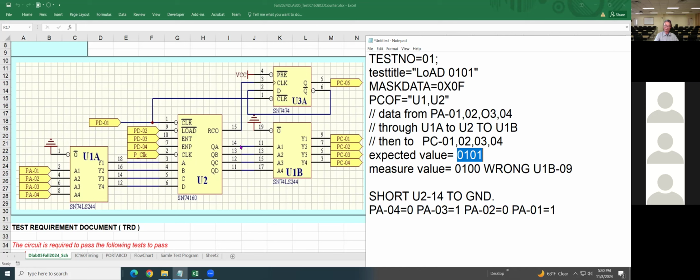In general, I said you take pin 9 wrong. You take pin 11 right. That's not enough information to tell you to change U1. You must check pin 19. If it's 0, then now you can say you want to change U1. That means you have to make sure the right input and the wrong output, then you can change the IC.